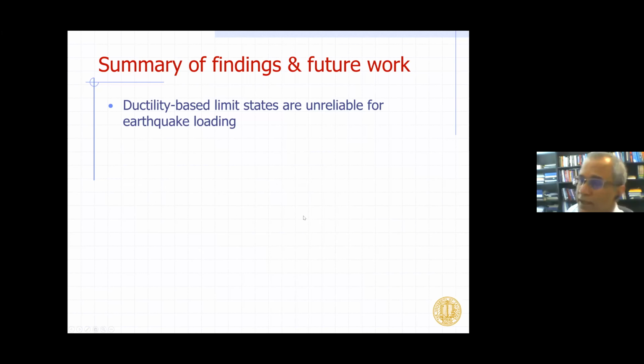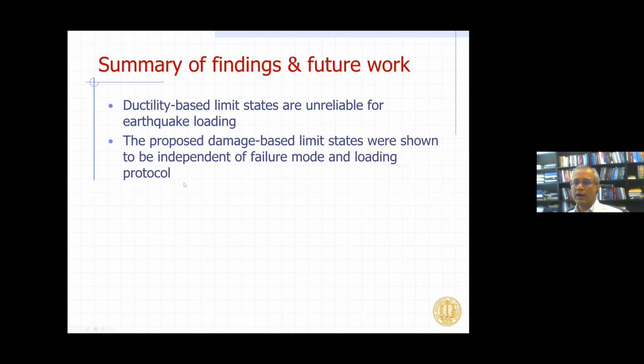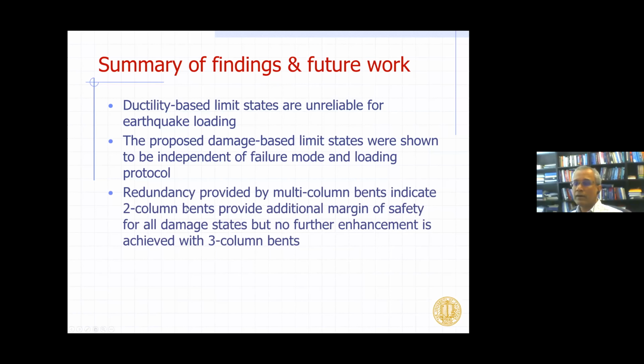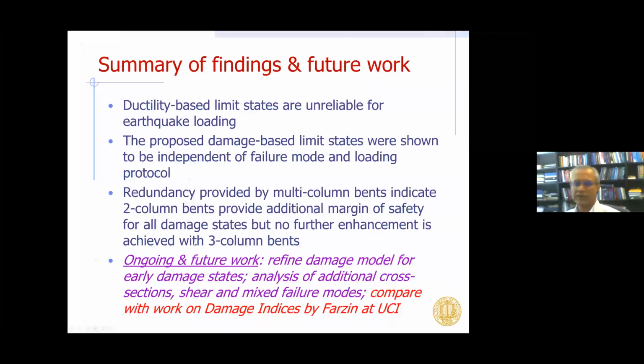So in my concluding slide, the few comments I want to make are that a ductility-based limit state is probably not going to be as reliable for earthquake loading, and the damage-based state that we have proposed was shown to be independent both of the failure mode and the loading protocol. I did not present results here of other failure modes, but we do have simulations of mixed failure as well. And as I just showed you in the previous slide, the redundancy provided by multi-column bents indicates that 2-column bents do provide additional margin of safety, but no further enhancement is achieved in going from a 2-column to a 3-column bent.